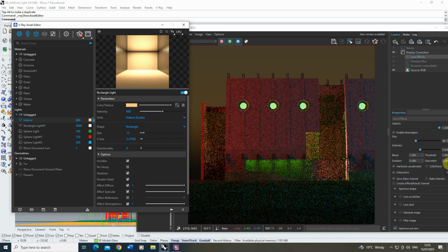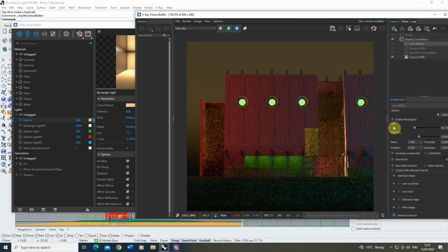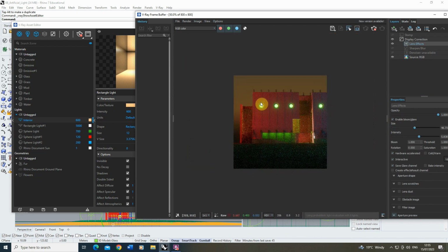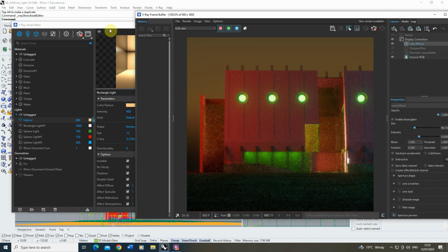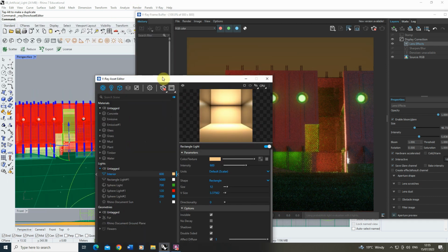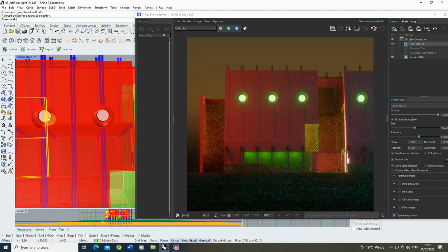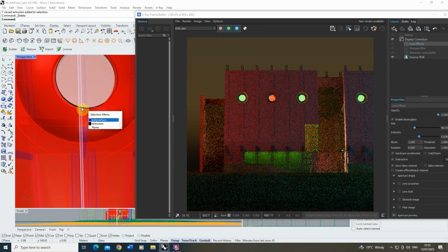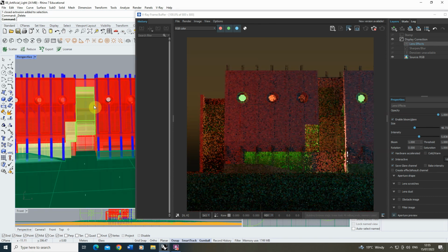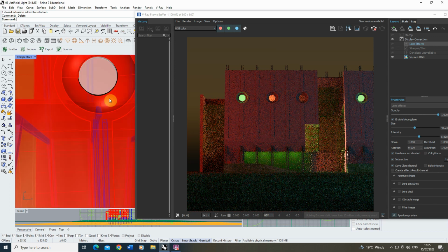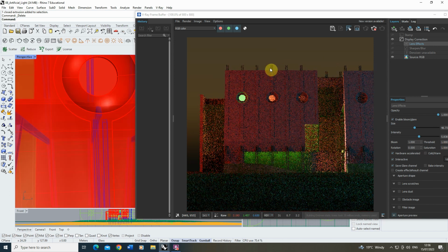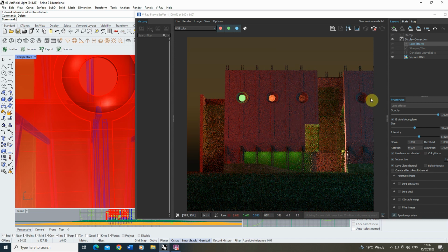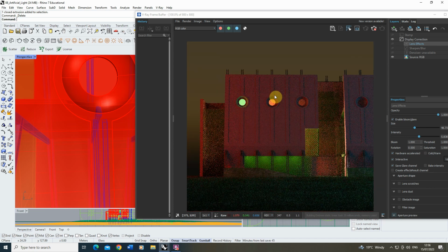If you wanted to make sure that bloom and glare is working, quite often you might have to turn it off, turn it back on again, and then it will usually reset itself. And I think somewhere like that is working well. Now I've got it to this stage, I'm actually going to take off a few of these lights I've put in here. Let's just delete a couple of them. And I think we might just have the one actually there that we'll be using, and then the rest will just be from internal glows inside. And I think something like that I'm happy with there.